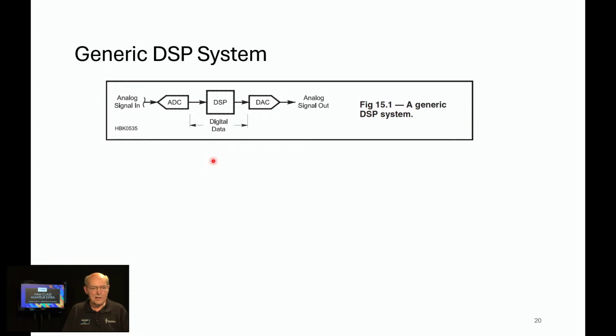So typically it's mixed down to an IF that is better suited to digital signal processing. Applications are notch filters, bandpass filters, noise filters, demodulation, and just all kinds of things you can do in the digital world. A lot of alphabet soup going on here. ADC, DSP, DAC, but as you see those, hopefully they'll connect.